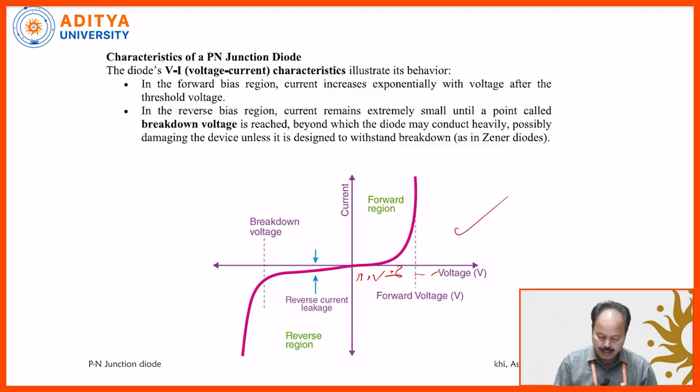So we get a curve like this, and as we are increasing the forward voltage, the forward current IF is increasing. Up to a certain voltage it is not showing anything, almost 0. Afterwards it increases a little bit, and suddenly it reaches almost infinity. Extrapolating this, it will cut the x-axis, showing the barrier voltage or built-in voltage or cut-in voltage. This is called the forward characteristic. Under forward bias we get it like this.